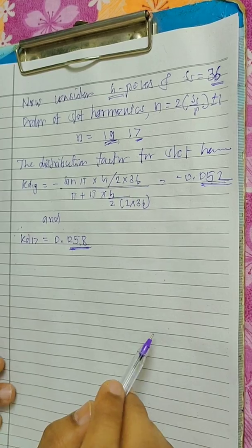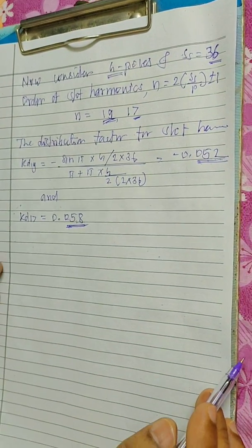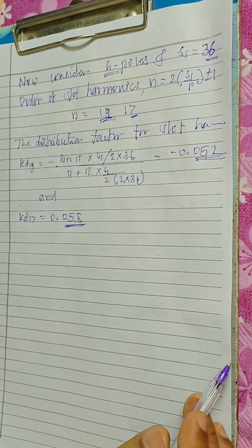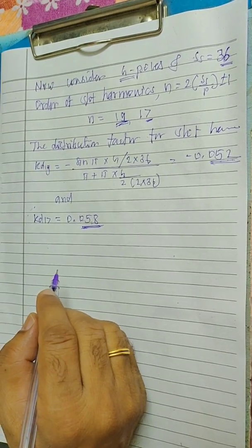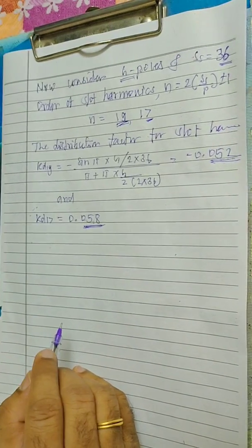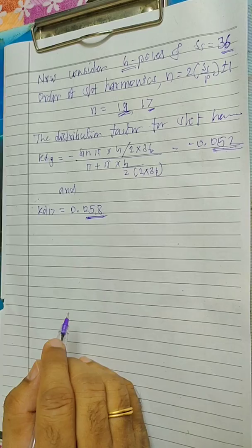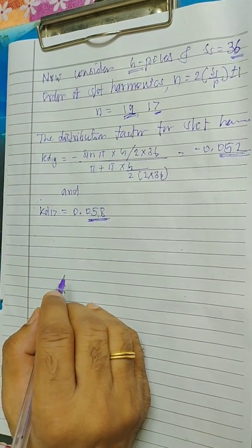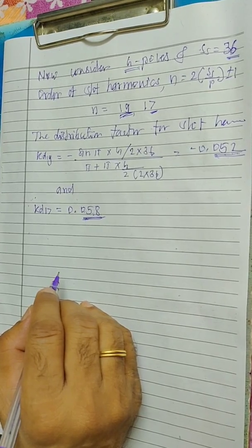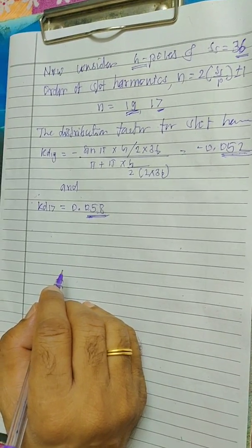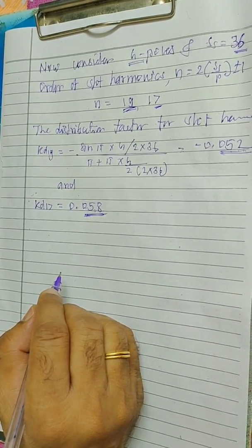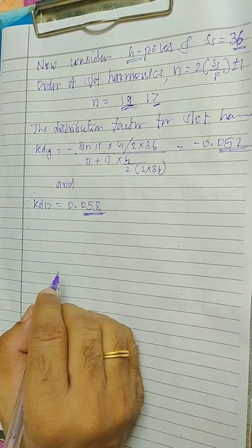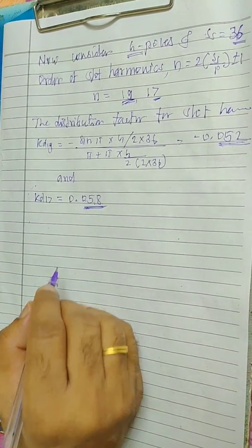The skewing of the rotor slot decreases the winding factor for the fundamental and therefore increases the leakage flux of the motor. Therefore, it lowers the power factor and the overload capacity of the machine.